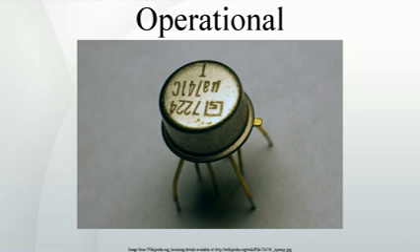It drives an active load, Q7 plus matched pair Q5, Q6. That active load is implemented as a modified Wilson current mirror. Its role is to convert the differential input current signal to a single-ended signal without the attendant 50% losses, increasing the op-amp's open-loop gain by 3 decibels. Thus, a small signal differential current in Q3 versus Q4 appears summed, doubled, at the base of Q15, the input of the voltage gain stage.